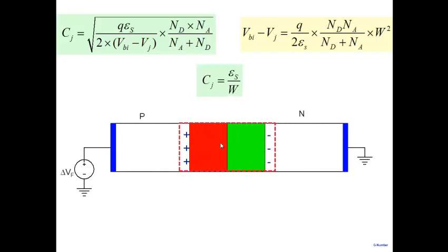And one can see why. As I said, if I earlier had a depletion region of some width like this, and I apply an excess bias here, the depletion width shrinks, and what has happened is the holes have come here and neutralized the acceptor atoms here. The electrons have come here and neutralized the donor atoms here. Where have those charges come from? The charges are here, and the charges are here. Those are the charges that have come from the external circuit. And what is the separation between the two charges? It is W here. So one can see a parallel plate concept here, right?